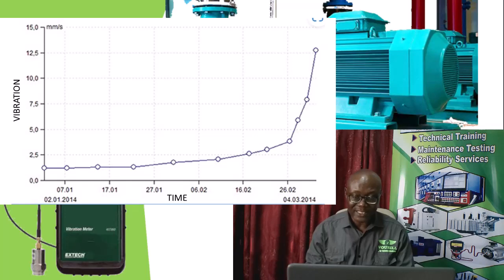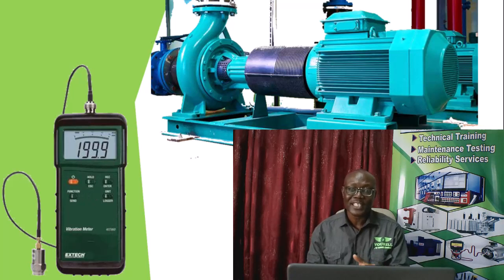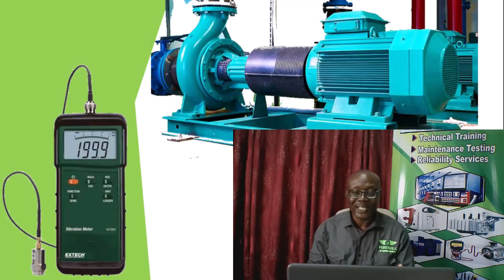And what is actually guiding this is the bathtub curve. Okay, so as that parameter, that is the vibration level that we are looking at, is entering the PF area, that is the point of potential failure and eventual failure area, you will see it with the handheld vibration meter that will give us the overall vibration level. So when it's entering that area, as the vibration is increasing, we can now use the vibration analyzer,